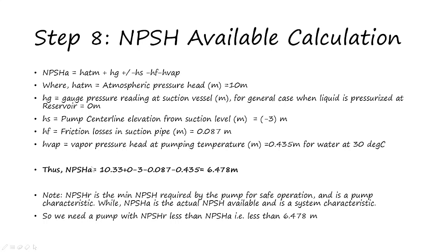Now this NPSH available must be greater than the NPSH required by the pump. The NPSH required by the pump must be less than this NPSH available. Then only this pump will work without cavitation. We will do the calculation and later on understand the concept with numbers. So, putting the values,